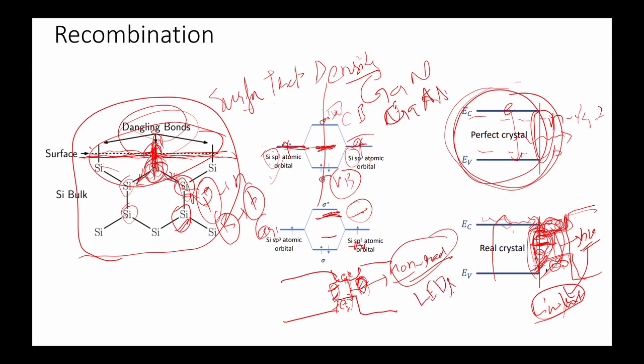Not only LEDs: if there are surface states at the PN junction, if we are making a heterojunction structure, one material and another material, there are surface states. If an electron is moving in this direction, it will be captured by the surface states at the interface.